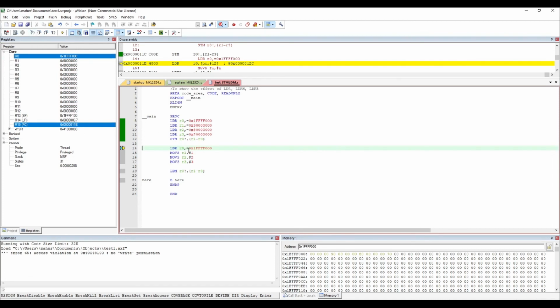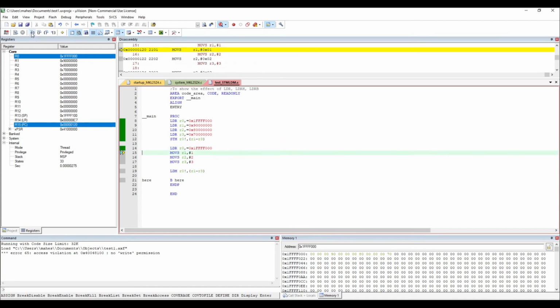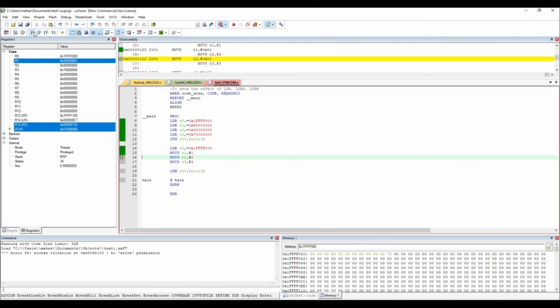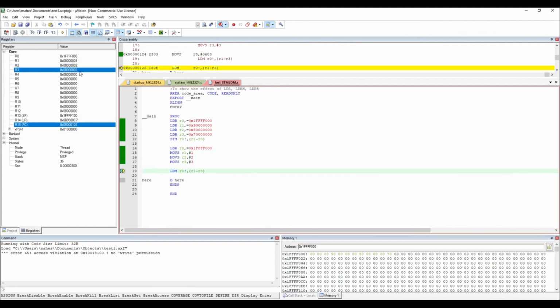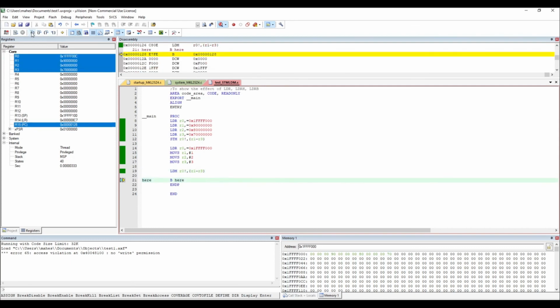Now I'm going to reload R0 with the original address. That's what is done. You can see over here also, if you search that address, this is updated with 9, 8 and 7. Now I corrupt R1, R2, R3 with 1, 2, 3, which I did using this move command, and now I'm going to load the register values from this particular address back to R1 to R3. Let's do that. Yeah, it's done. R3 is loaded with 7, 8, 9 as before. So we recovered the data fully.